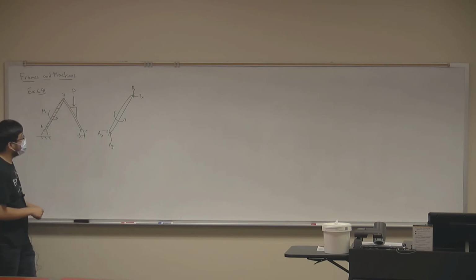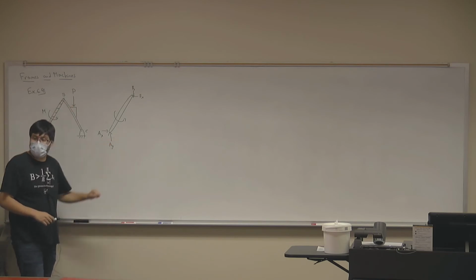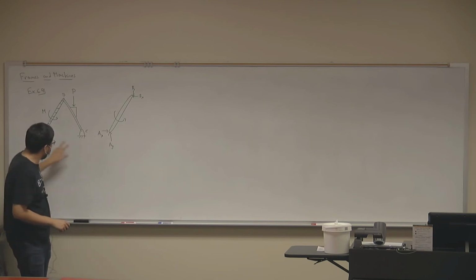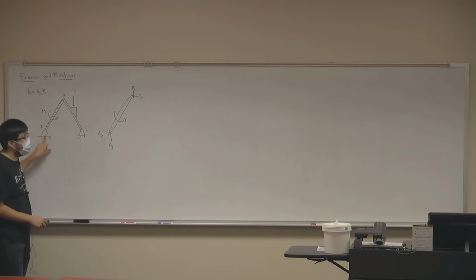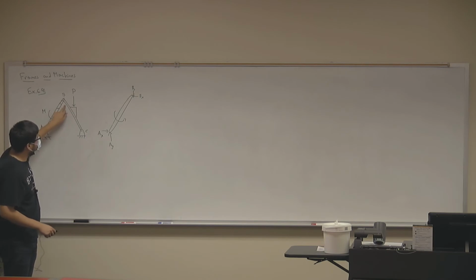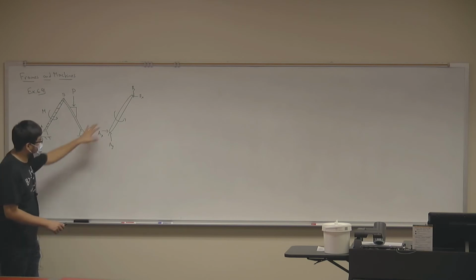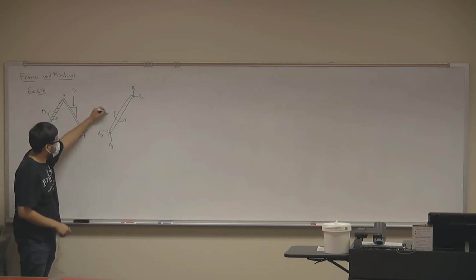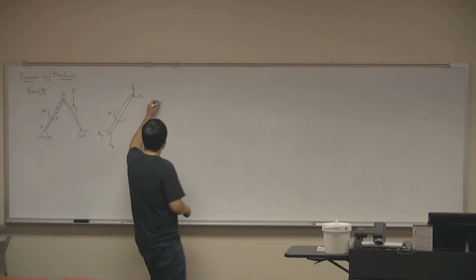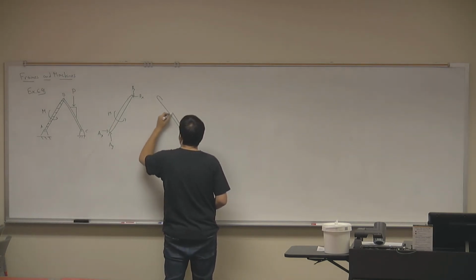Okay. So you have your forces on AB. Notice that we're identifying not just the reaction forces from the hinge, but we're also identifying the forces that result from the connection between AB and BC. Does that make sense? And of course the moment that we already included. Now let's look at frame BC.